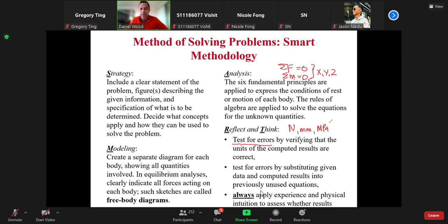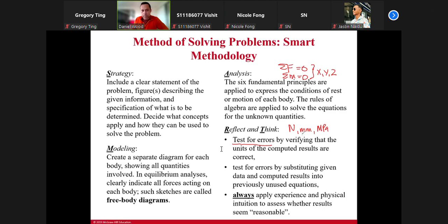That is consistent units. I could tell you another set of consistent units, which are newtons, meters, and pascals. You can do that as well, okay? But I want you to be consistent all the time. And typically, millimeters is the engineering dimension that we would use, okay? Mass is kilograms. Kilograms, not tons or anything like that. It'll be kilograms, okay?